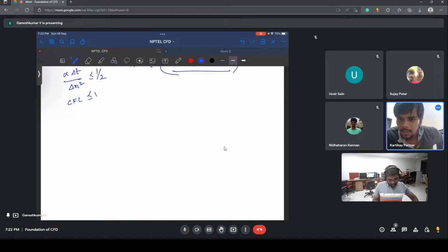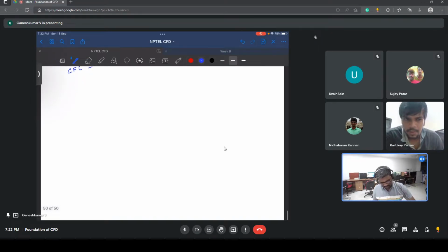Well, it's not the reason. The reason for using ghost cells is to implement the boundary condition. There is no reason like I starting from 2. The only reason is to implement the boundary condition. Let me give you a simple example.